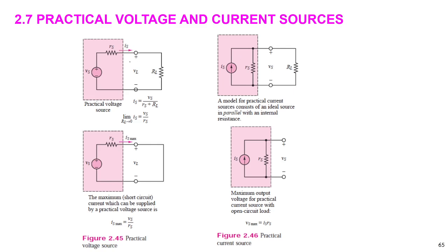In this case RS is very low for a voltage source, but for a current source RS is very big. It means almost open circuit, right? Very big is similar to open circuit, and very small is short circuit. So we just calculate as ideal sources, right?